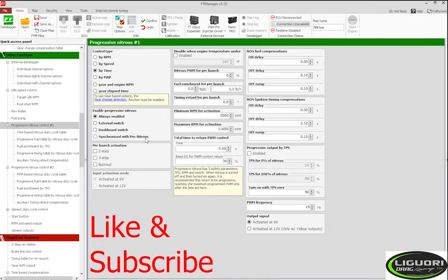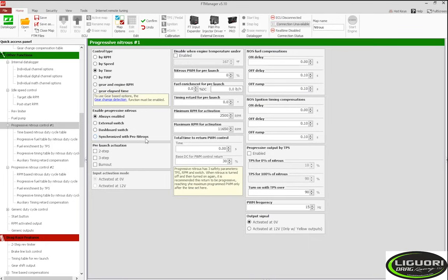And what this means is your bike will not, I repeat, will not spray nitrous if there is no validated launch. So for example, if you get crazy and you're 90% throttle in the burnout, maybe when you're pulling out of the burnout or something, you wick it, it's not going to spray the nitrous because you didn't go up on the two-step first. If you go up on the two-step before you do your burnout, then it can trigger a validated launch and then ultimately spray your nitrous. But if you don't do any of that, if you don't go up on the two-step, then you don't have to worry about that at all.